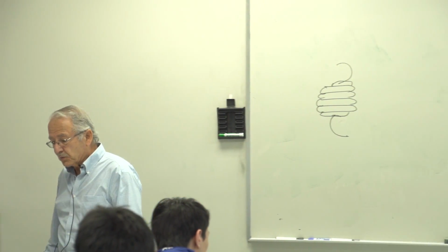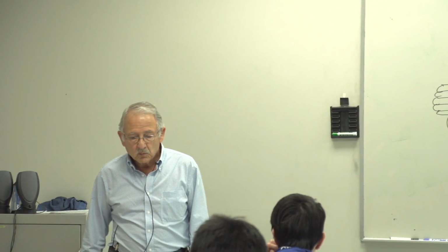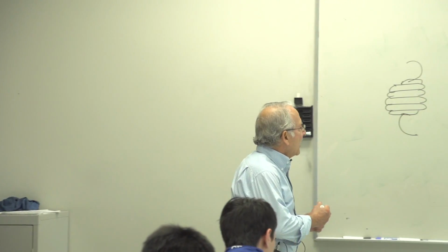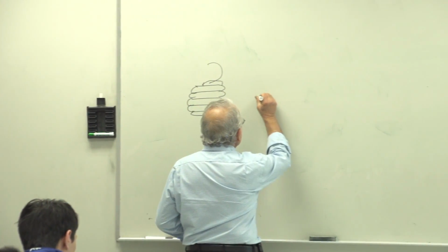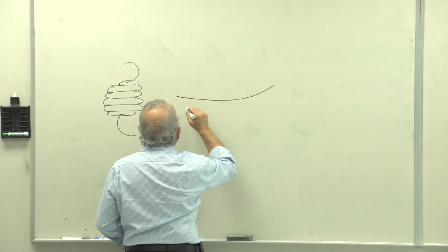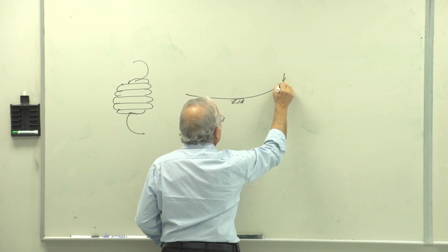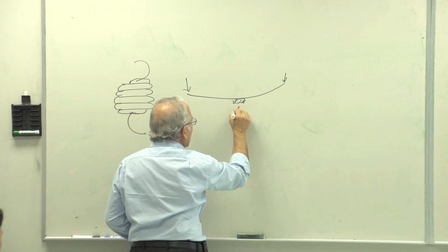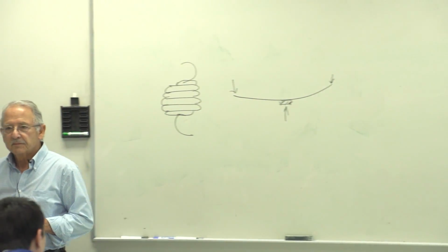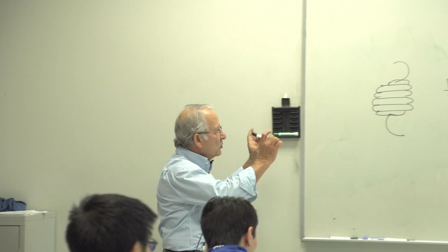You can also have springs which produce deflection by bending, such as a car leaf spring. They don't use them that often anymore, but if you look at old cars or trucks, they do use leaf springs. These give you deflections through bending.